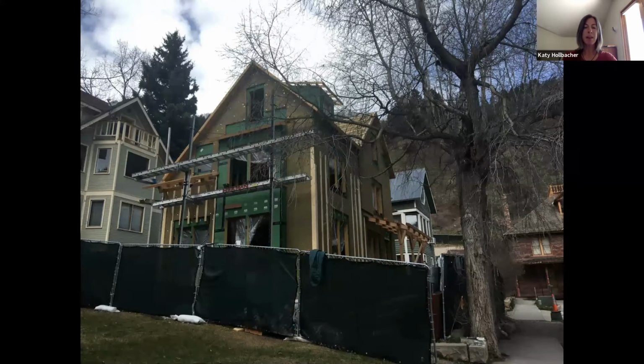But essentially, the Passive House standard is built on these best practices I just talked about, which is, hey, let's first just design good building envelopes to minimize heating and cooling demand. That's where we should start. So this project took a kind of a pragmatic approach, definitely went above code, but didn't do anything that some people might call extreme. So this dark green you're seeing here is a sheathing panel called Zip System, which I'm sure a lot of you are familiar with and have worked with.